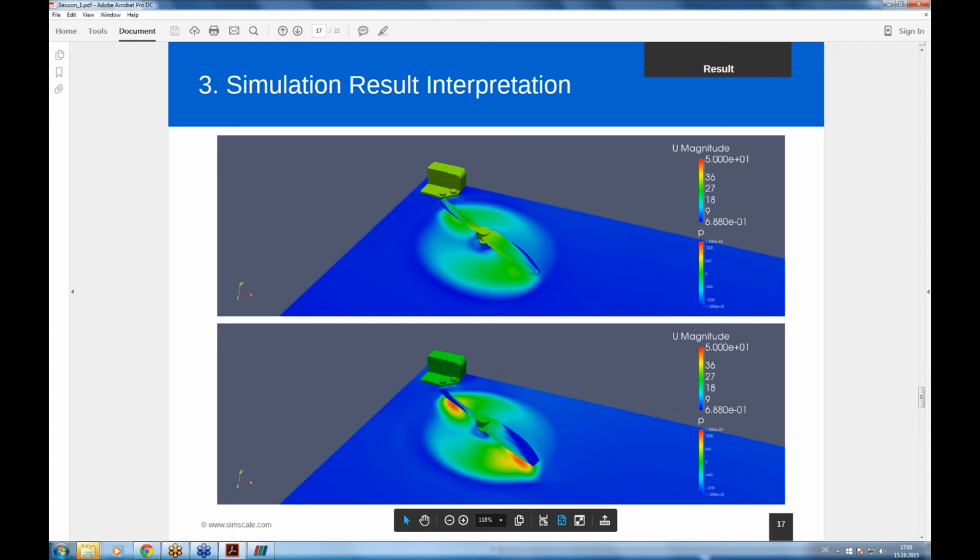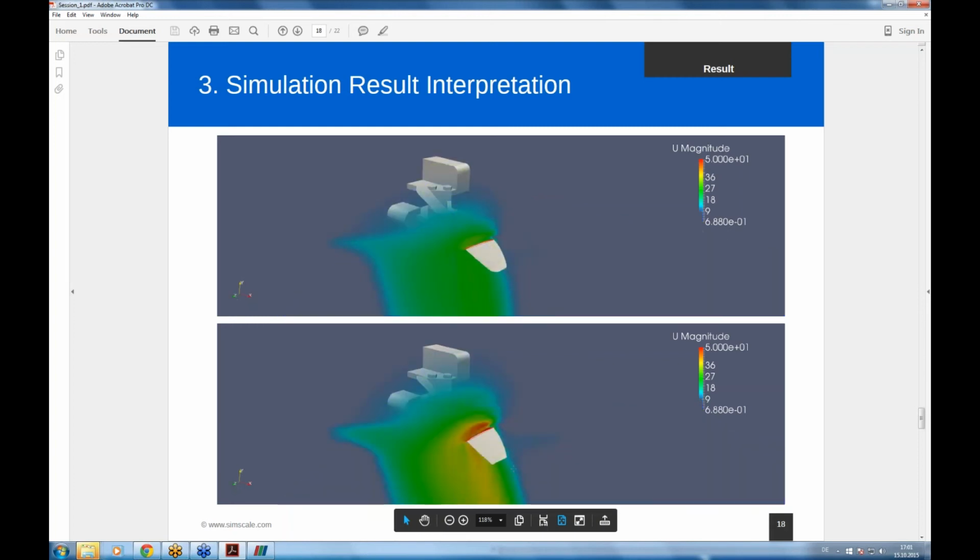and you can really see that here you have much more flow streaming through. So if you would like now to optimize the wing, what you could do is, instead of just taking a look at the forces, try to change the shape in a way that would make this red area bigger. And here it becomes really obvious. This is the velocity again. In this case, it's a cut through the profile at the same place. And you can really see that this lower design is accelerating the flow so much more, and that's, by the way, the reason why we have this higher suction.